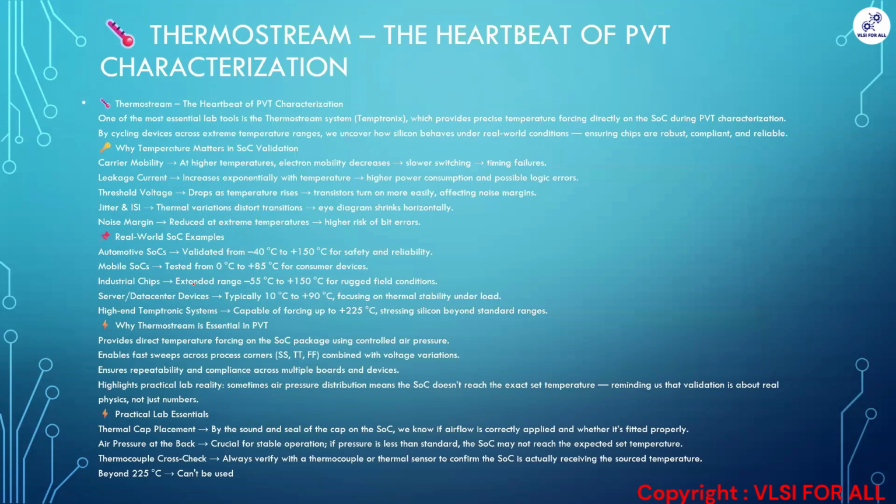Next, we will be going to see the Thermostream. Thermostream is mostly used for PVT characterization, PVT characterization of any SOC or any transistor. We'll use that PVT to see, when we give the temperature, how the silicon or the transistor is behaving.